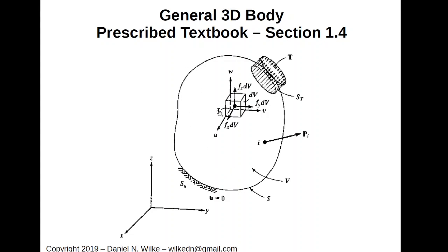And the difference between a body force and a point load or traction is that a body force acts at every point in the volume. Every point in this body experiences a body force, whereas the load is applied at the surface. And here at the top, the surface traction is applied at the top of the surface. Okay, so the question is, what are the units of these body forces? The units of the body forces are typically newton per volume. So if I take a newton per volume and multiply it by the differential volume, this fx dV then becomes just newtons.